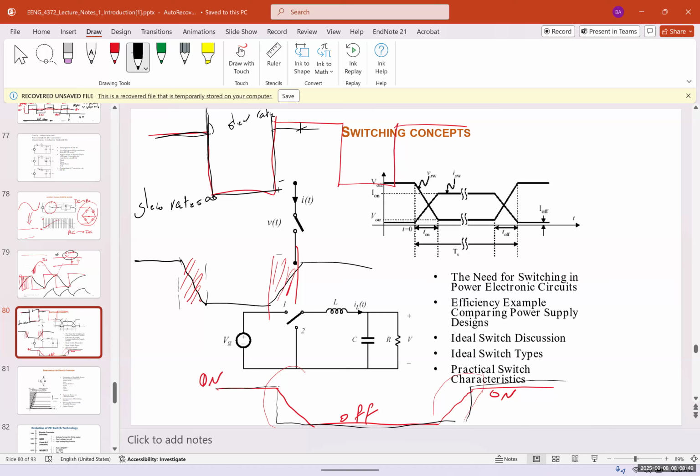And all of these go back to frequency response. If we have an op-amp or a transistor that has a very high bandwidth, a very high frequency response, you're going to have a very fast switch. And if you have a transistor or an op-amp that has a lower bandwidth, you're going to have a lower frequency response and a slower switch. And these are examples of the swing rate, and they also call it the slew rate.